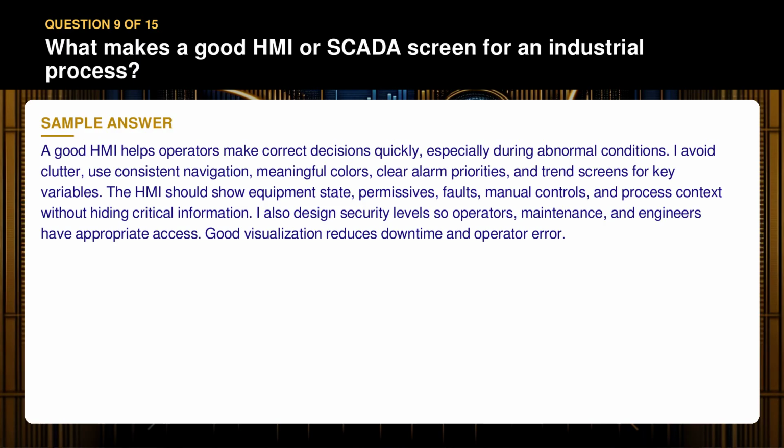The HMI should show equipment state, permissives, faults, manual controls, and process context without hiding critical information. I also design security levels so operators, maintenance, and engineers have appropriate access. Good visualization reduces downtime and operator error.